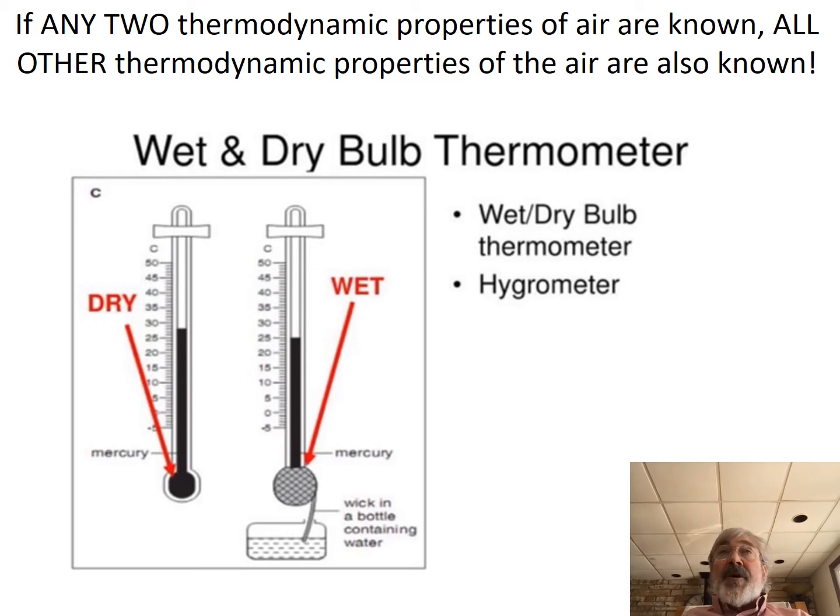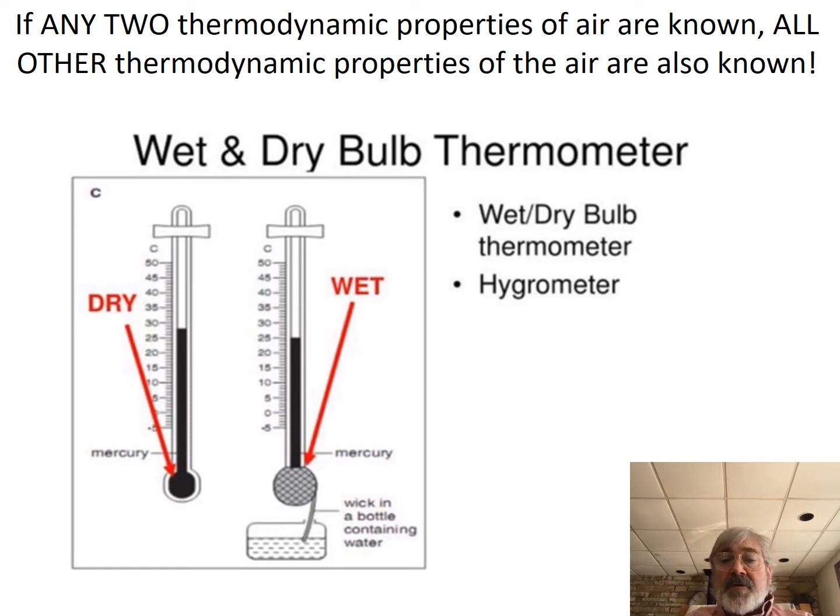I've had lots of experience with electronic hygrometers and electronic relative humidity sensors, and they're very expensive and they do not survive kilning, and they give poor information. So my recommendation to you, if you're out to learn a second psychrometric property of your air, is to utilize a wet bulb thermometer in as many cases as you can, and then possibly use what you know about psychrometrics to extrapolate other properties off of that. And I can try to show you what I mean by that.